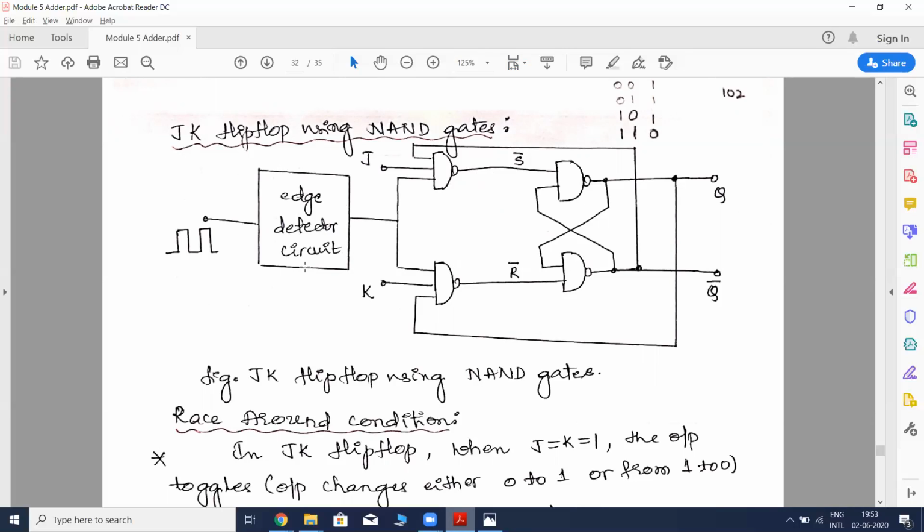So in this JK flip-flop, first, why we are coming for this JK flip-flop is a point. First we discussed about the latches. Upon disadvantages with the latches, because they all work on the asynchronous inputs, we want to synchronize that one. So we came for flip-flops. First we discussed SR flip-flop. The problem with SR flip-flop is that when both the inputs are equal to 1, 1, that particular condition is known as the indeterminate state.